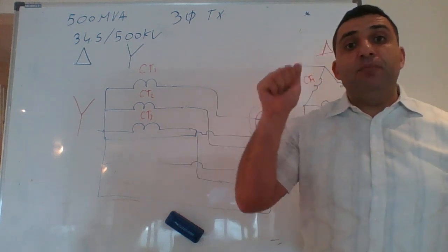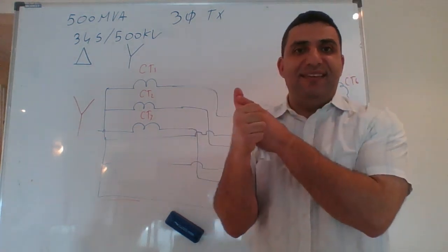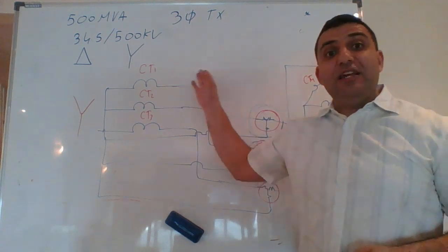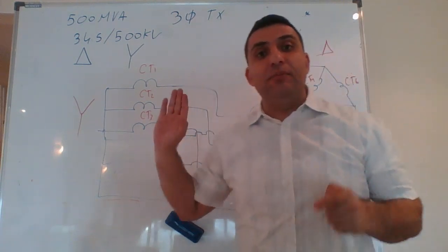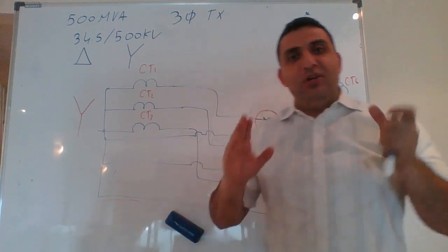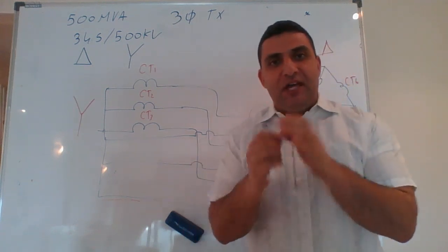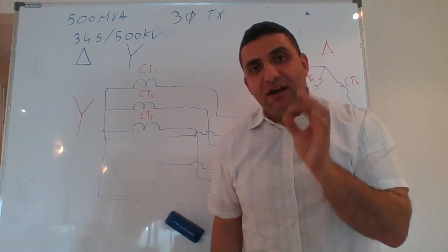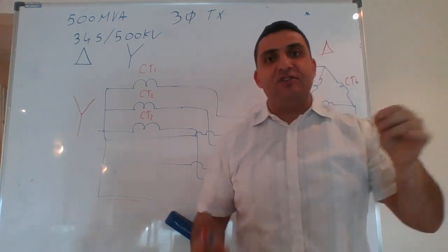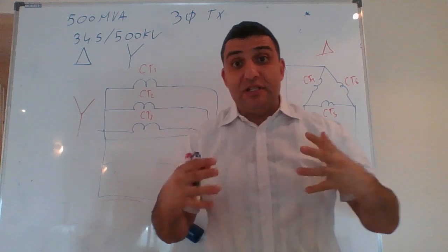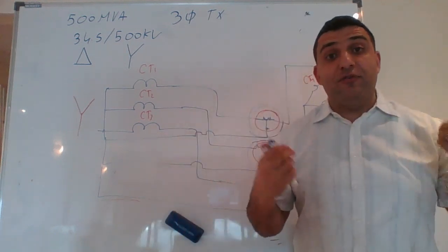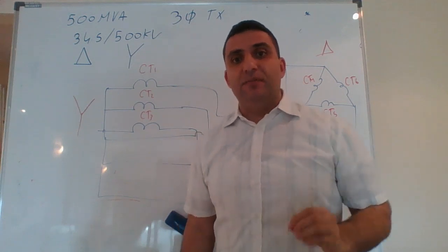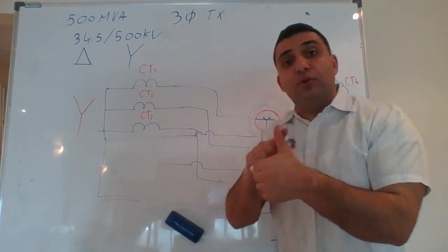There is a very important element. Number one is I need to make sure that I take into consideration the shift angle between delta and Y. When you have a delta and a Y, when you have a delta, for example, the phase current and the line current are shifted by 30 degrees. We discussed this in detail during our phase 2 week of this course. Please refer back to the material. That's one element. It's very important for me to note.